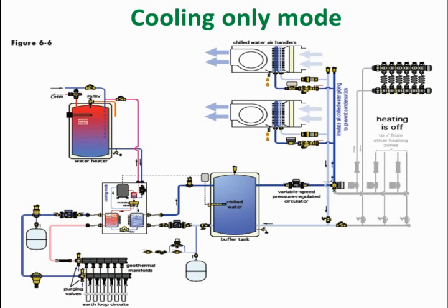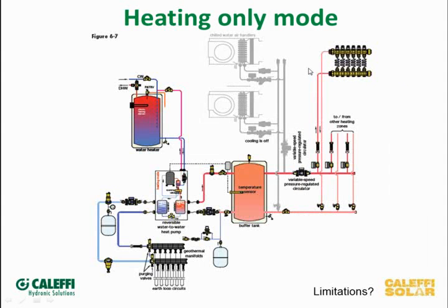Here, you can see we've grayed out the heating side of it now. When we're in the cooling only mode, this is what's happening with that tank. You'll see on the next slide, we're going to switch off of the cooling mode and turn this into a hot water buffer tank. So there we are. The cooling load has gone away, but we do have a heating load.